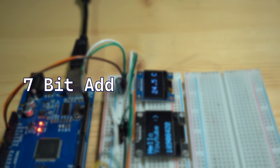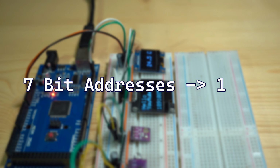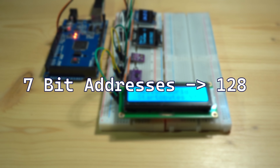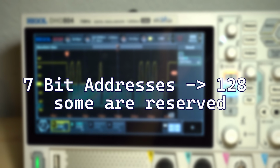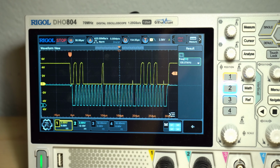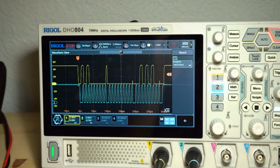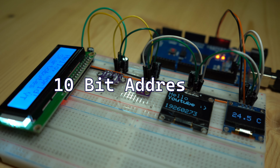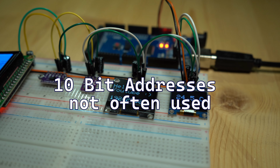Most I2C systems use a 7-bit addressing system, which allows up to 128 addresses, although some are reserved for special purposes. In applications where we need more addressing space, I2C also allows 10-bit addressing, although that's not really used and not very common.